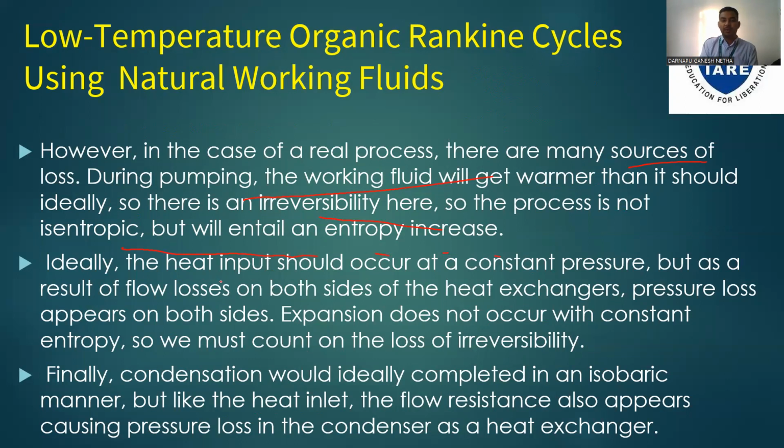Ideally, the heat input should occur at constant pressure, but as a result of the flow losses on both sides of the heat exchanger, pressure losses appear. Expansion does not occur at constant entropy, so there is irreversibility. Finally, the condensation.